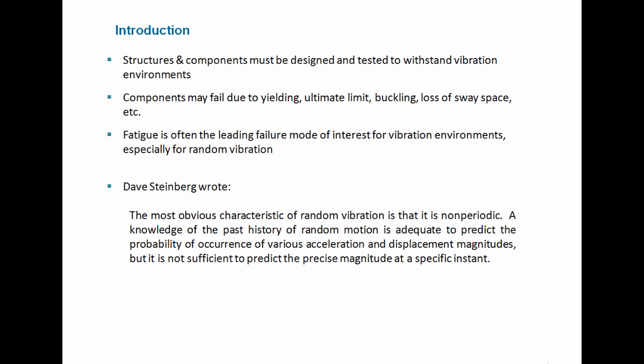And previously we've discussed Dave Steinberg's quote, but let's review it. The most obvious characteristic of random vibration is that it is non-periodic. A knowledge of the past history of random motion is adequate to predict the probability of occurrences of various acceleration and displacement magnitudes, but is not sufficient to predict the precise magnitude in a specific instance. So when we're dealing with random vibration, it all becomes a matter of probability and statistics, and that will certainly carry over into our rainflow fatigue analysis.